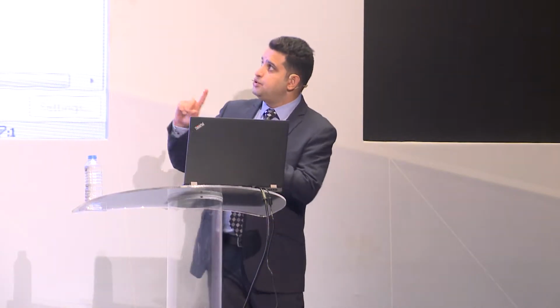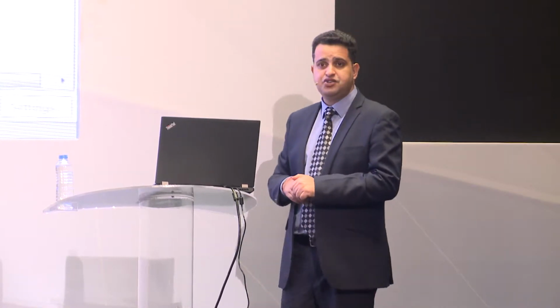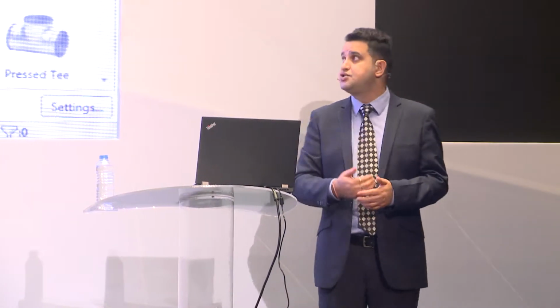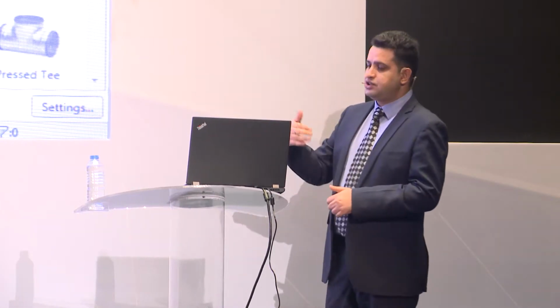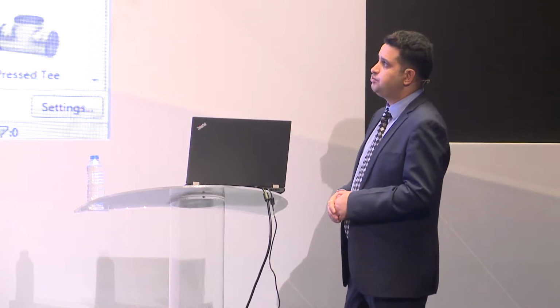If you're familiar with Revit MEP, it looks similar inside Revit MEP, in the modeling portion, whether you're modeling the ducts, the pipes, or the cable trays, and you can start looking at the solutions. The beauty of these fittings, or these connections, is that they are as per the specifications for fabrication. They come from manufacturer content. So you do not need to worry about whether my fitting is correct or not. These are not generic fittings. These are ready-for-construction fittings by default. Similarly, if it was a duct or a pipe, you'll be able to look at them, customize them, and fabricate them at any point whenever you need them.